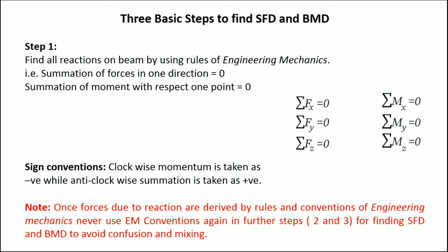That means, for example, summation of all forces in one direction. Let us say summation x. Here you can see summation Fx, that means forces in the x direction, or in the direction of the x-axis, will be equal to 0. Similarly, put in all these formulas. Generally, we will have to use this Fx and Fy in the case of the beam: summation of Fx equal to 0, summation of Fy equal to 0, and the next equation or method. We are talking only about step 1, finding the forces.